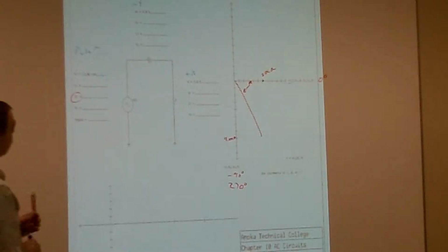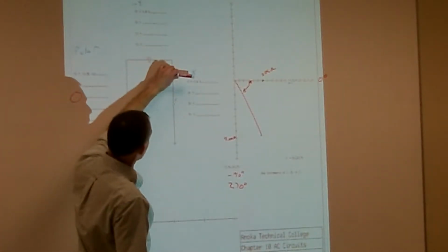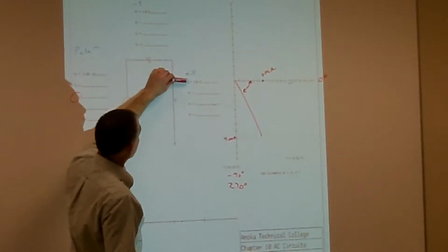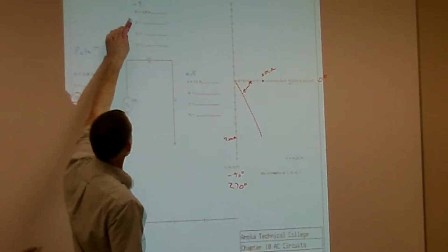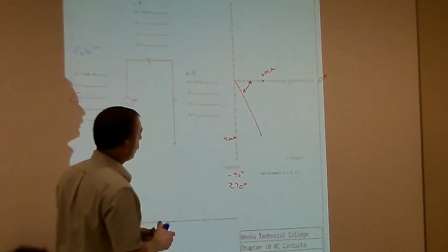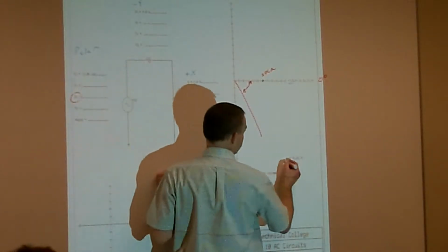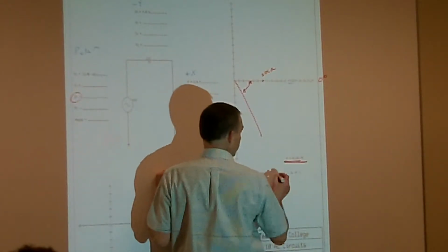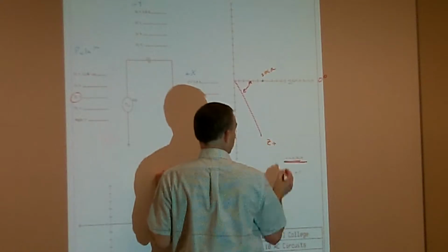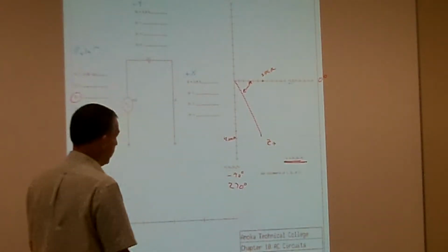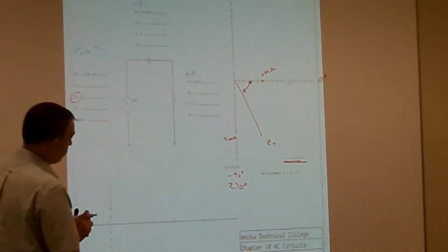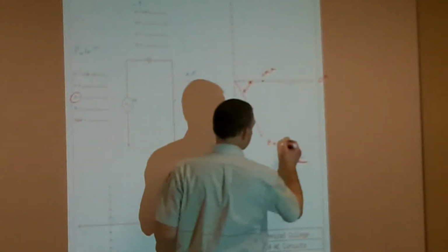All right, so by entering this into my calculator, I get next, my resistor is 3 kiloohms, my capacitive reactance is 4 kiloohms. What do I get for the length of my line here? That's this one right here. That's going to be my ZT, my impedance, which is a combination of. So what do I get for ZT?